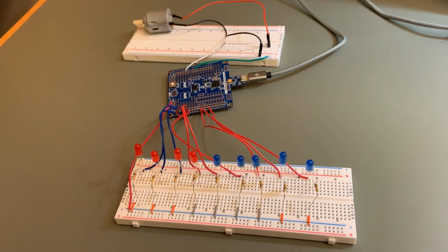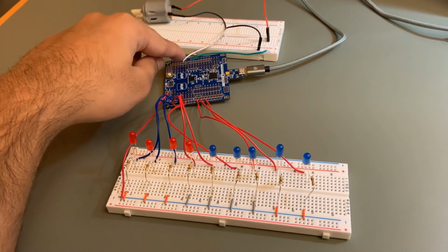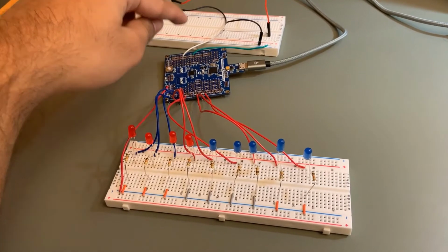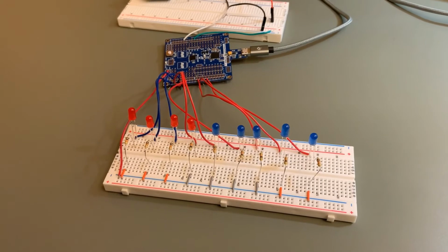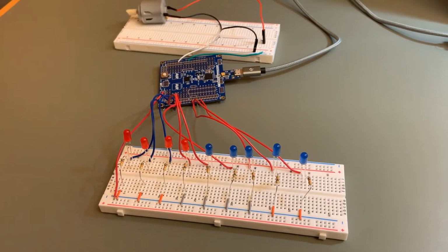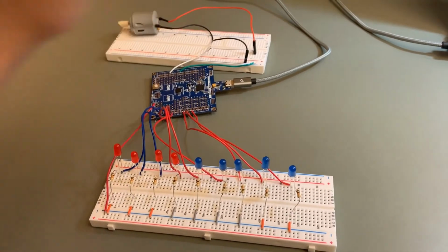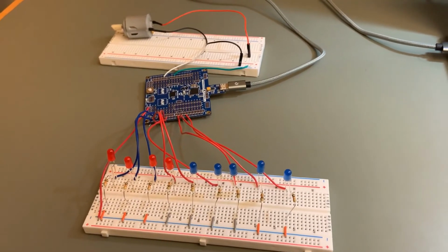Now, the way it works is that we have a hobby motor connected to a pin of port C. When we run a program that turns that bit on, we supply 5 volts to that pin, which powers up the hobby motor, and then it's connected to ground to complete the circuit. We have used the same concept for these LEDs as well.